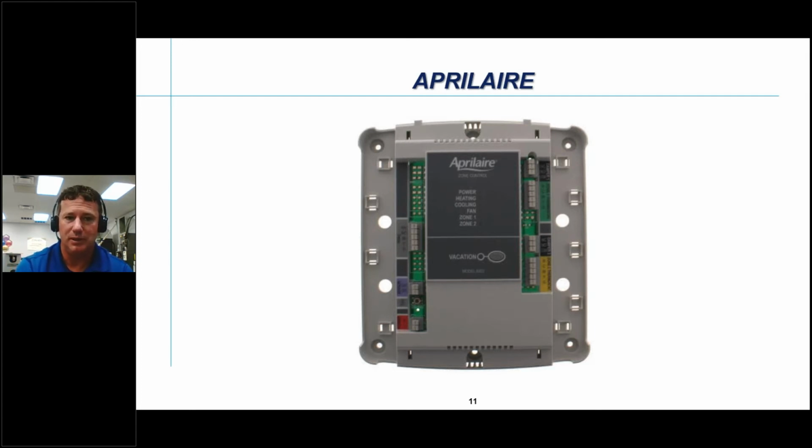Now we're talking something that we can do. Now we can take a communicating modulating system and we can put a traditional zone control on it. Because remember, the zone control really is all about modulating a signal off from our thermostat. So it's really just a control. It's a secondary switch for our primary switch.